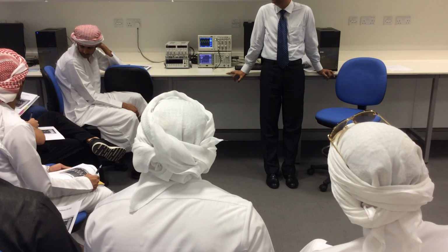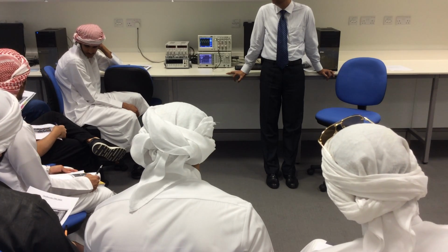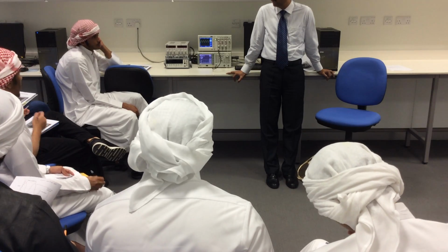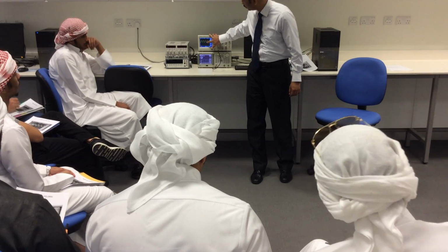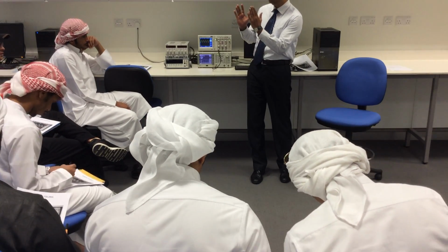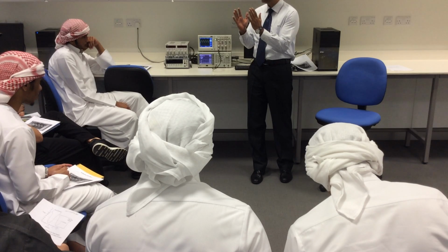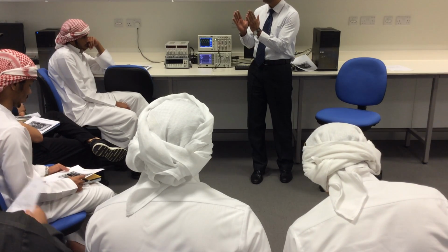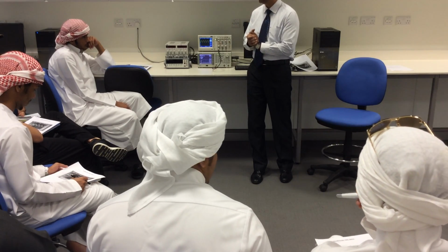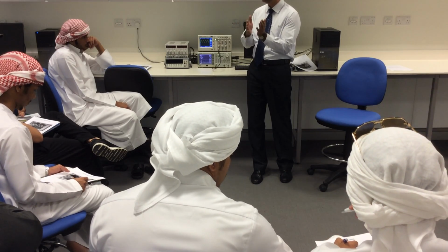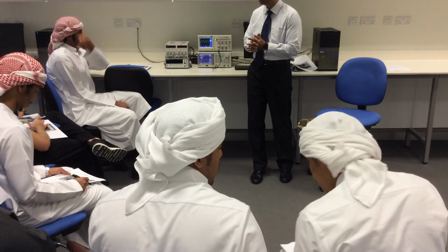I didn't understand the last one, the frequency. How can we do it? The time is the time period. So how do we find the time? This is 1 block, 2 blocks. So 2 blocks for 1 full cycle. And 1 block is 5 millisecond. So 2 blocks represent 10 milliseconds. So this is the period. So for 10 milliseconds, if you take 1 over it, you will get 100 Hz. 1 over period is frequency, or 1 over frequency is period. Make sense?